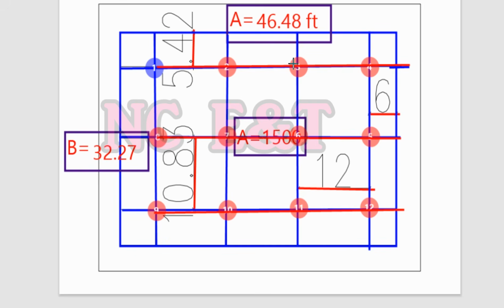These are two sprinklers on the same branch, and we denominate it by S. And these are two adjacent sprinklers on the adjacent branch, we denominate it by L. Area A equal to S into L. So it is the protection area by one sprinkler. So I think it is clear.